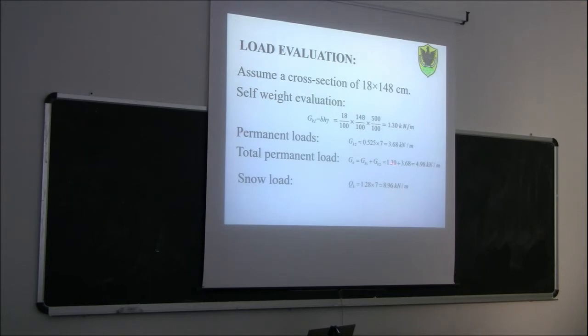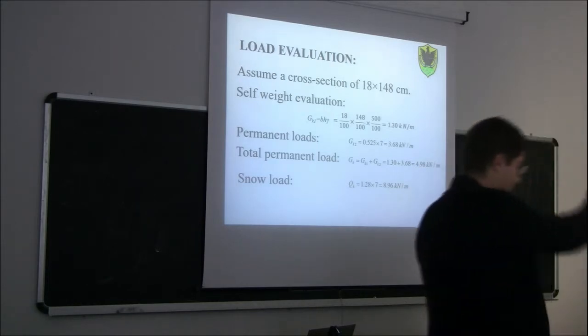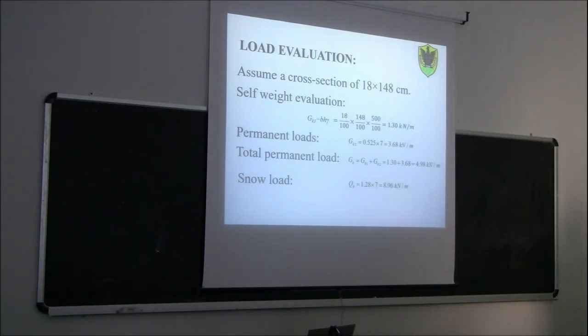Nevertheless, note that it's still important, because the self-weight is more or less 1/3, let's say 1/4, of the total permanent load. So also here we need to be a bit careful, because this timber beam is quite big. Almost 1.5 meters, almost as high as me, and 22 meters long. So it's quite an important percentage. Okay.